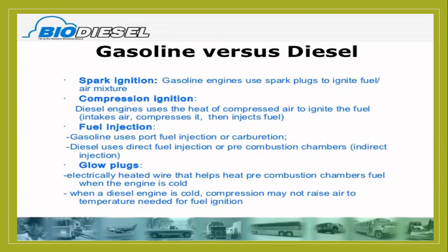So they need pre-plug. Pre-plug means sometimes before the spark plug power, the fuel will go through one heated line. Heated line. They have some plug in the, we call inlet manifold. Inlet manifold have some glow plug. Some motorbike also you can see.